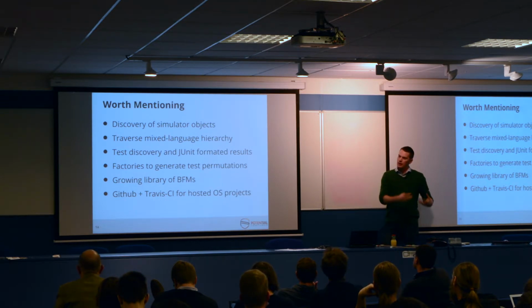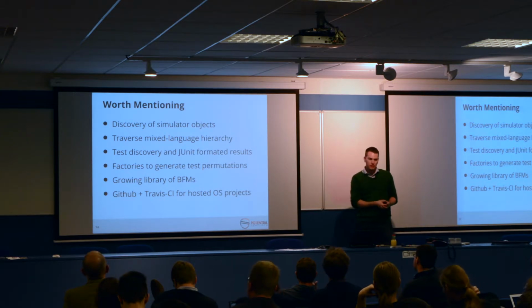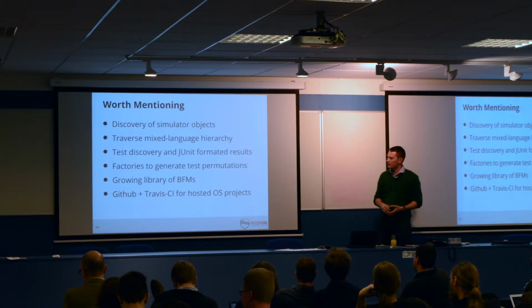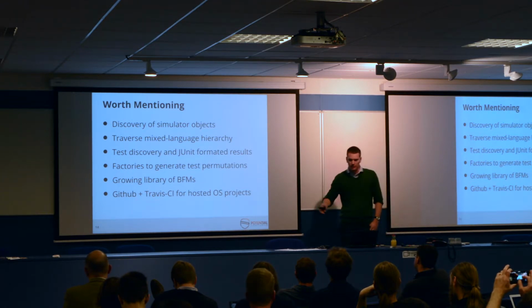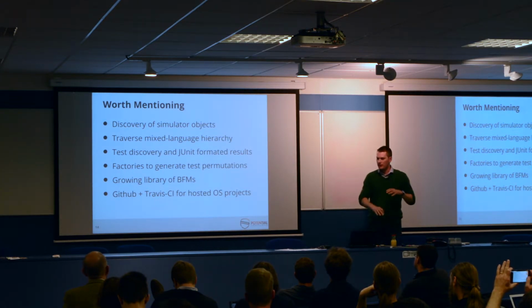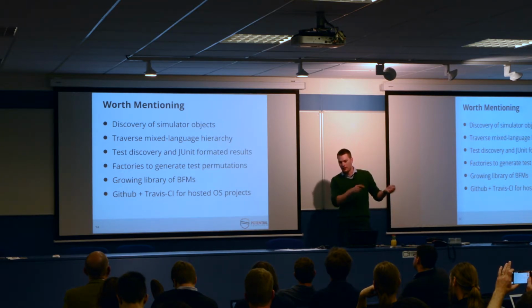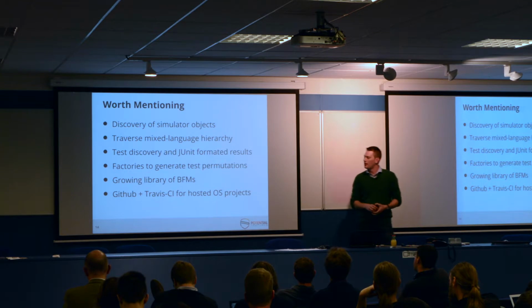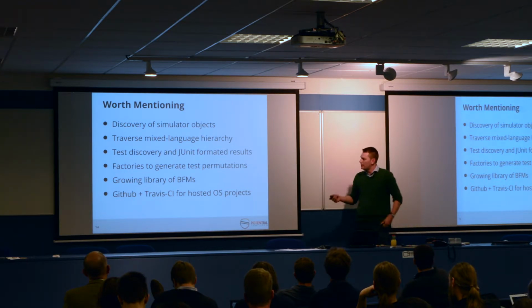So the discovery aspect and the dynamic introspection that you have available in Python is very powerful. Your design can be VHDL or SystemVerilog. You have mixed layers of hierarchy, and the interface from Python is always the same, so you can traverse through the language barriers without knowledge of what language the design is in.